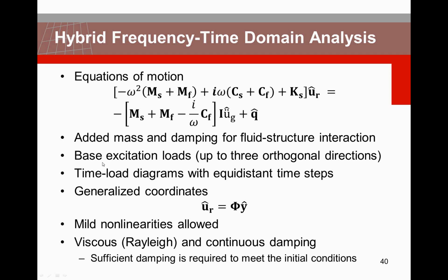The loading is limited to base excitations. These are given in the time domain as accelerograms, but internally we are using Fourier transforms to transfer them from the time domain to the frequency domain and back to do this iterative process. It requires that your time load diagrams have equidistant time steps, because that's needed for the Fourier transforms and inverse Fourier transforms.